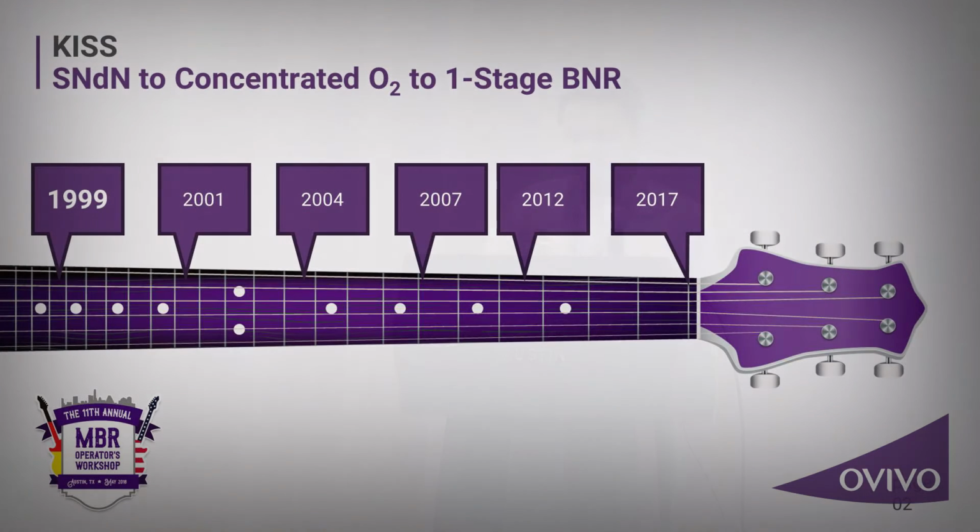The focus of this presentation is that you will see different case studies where monitoring a particular specific process parameter improves your membrane performance, or how controlling the process through online data monitoring can help you meet really low nitrogen numbers. In 1999, we started with a process called Symbio, which is simultaneous nitrification, denitrification happening in one basin. Basically, we are controlling the parameters within the one basin, controlling the aeration and SRT in a way that you can nitrify as well as denitrify.